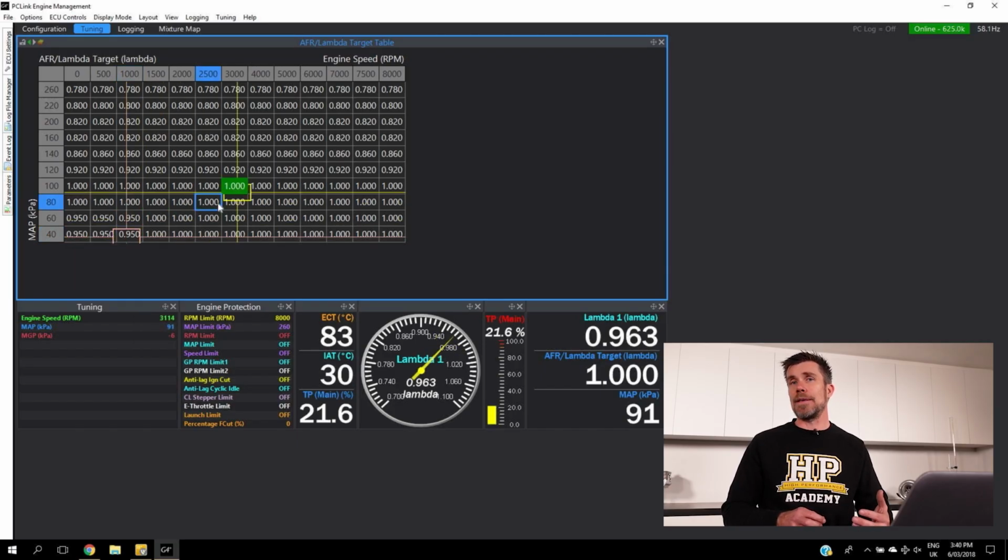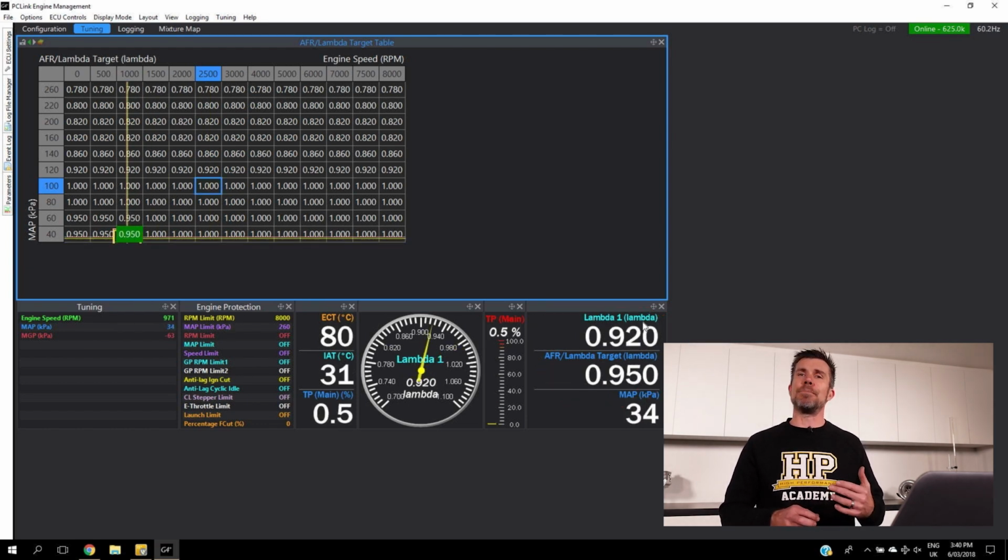There are a few other intricacies though. If your ECU allows, what we also still want to do is incorporate that manifold absolute pressure signal from our balance bar into a background fuel compensation. To try and make it really simple, the principle here is that if we double the manifold pressure, we need to double the amount of fuel, or the mass of fuel, being delivered in order to maintain the same air-fuel ratio. That's one of the principles behind speed density anyway.